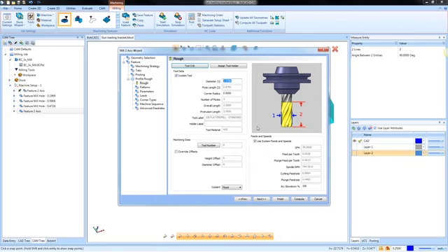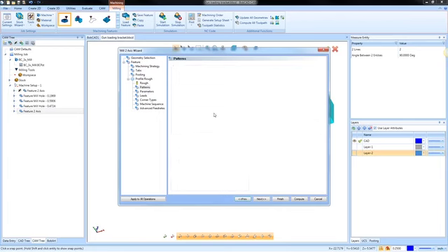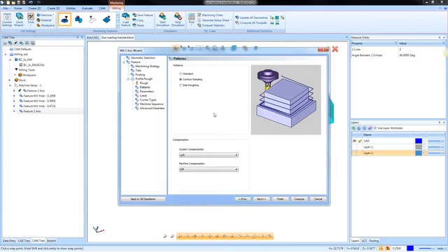Tool size, I'm just going to put an 1/8 inch end mill, something that I know will fit in there. And then our pattern here, instead of a standard, I'm going to do contour ramping. And contour ramping you can use for slots, you can use it for holes, you can use it for roughing outside shapes. Contour ramping will ramp down to the bottom.